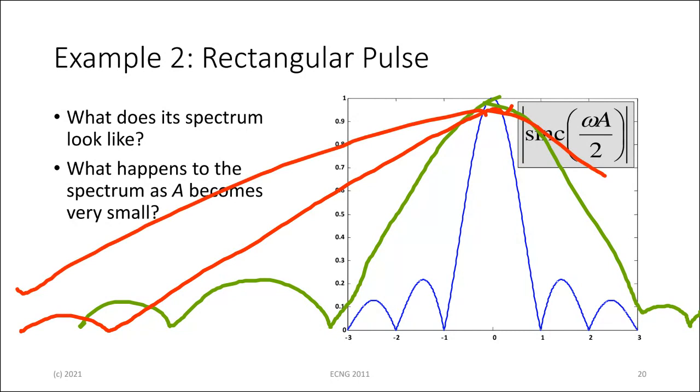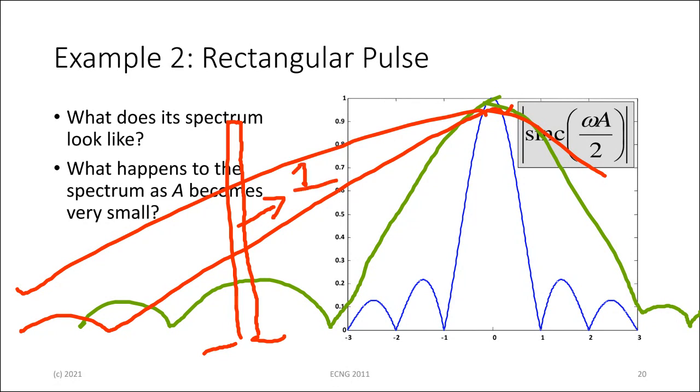Eventually, the limit, of course, is when a is 0, so that you have a 0 width and an infinite height, which is a unit impulse. Of course, you can't get that, but what we are seeing is that if I can make a pulse that is fairly narrow and fairly tall, once I retain the area as 1, I can get a function whose frequency response is very, very flat over a long range of frequencies.